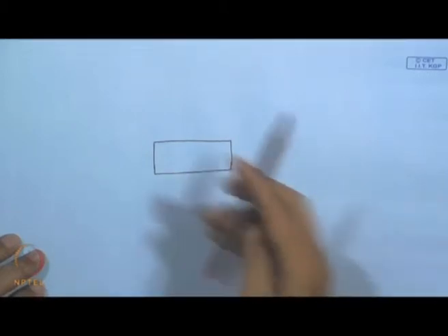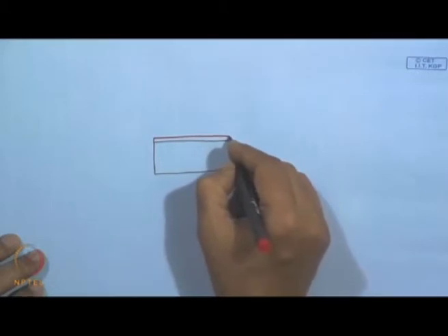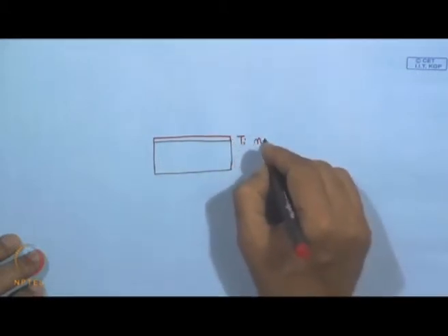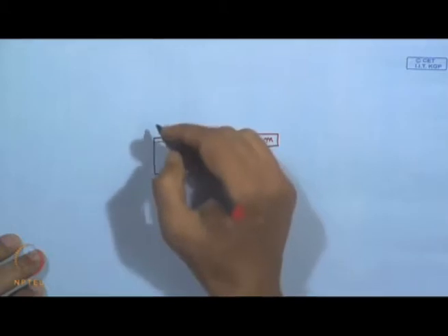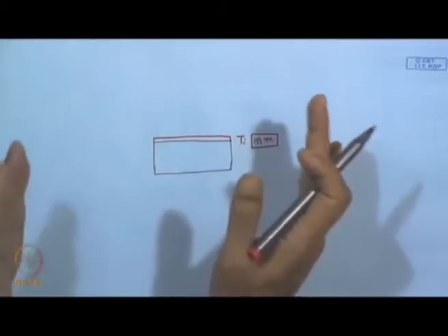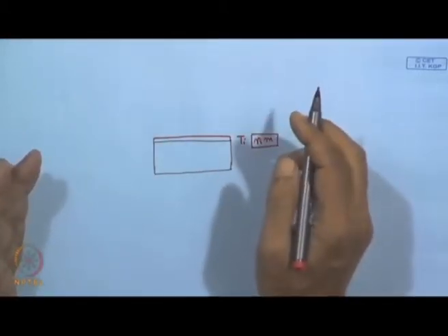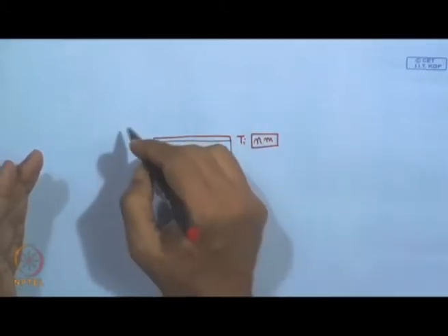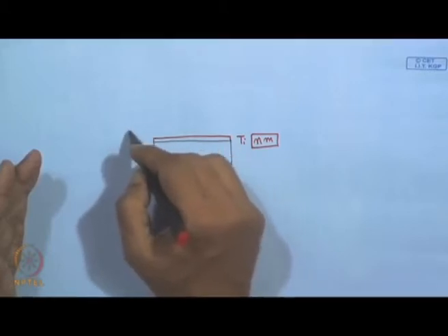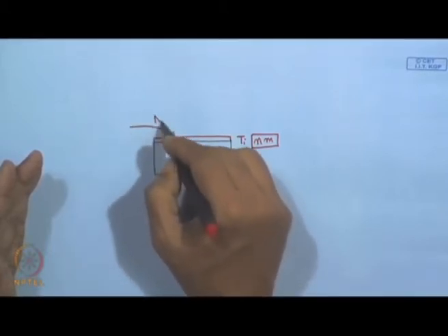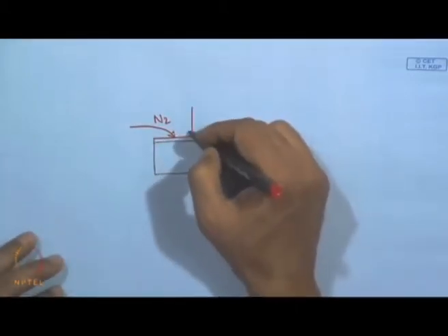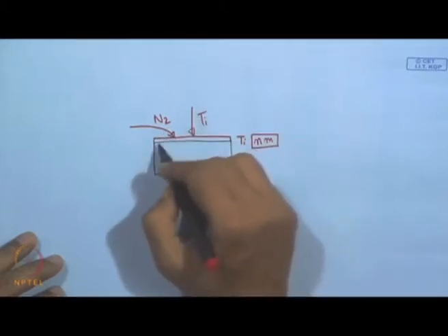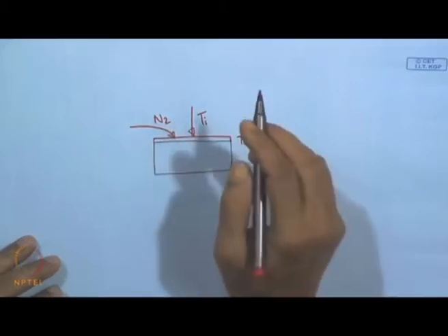With this substrate we have a titanium layer at the nanometer level, and on that starts the deposition of titanium nitride. That means, after a few minutes of passing this titanium flux, one can start admitting nitrogen from this side. The nitrogen will also be ionized, with the continuous flux of titanium also arriving. So, on this surface we have titanium nitride.